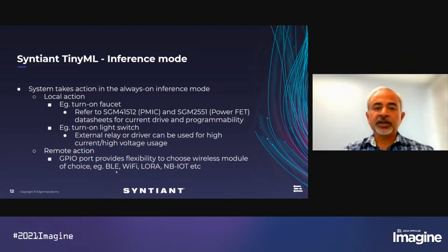Now you can also choose a BLE interface, you can use Wi-Fi, as well as you can use NB-IoT modules, GSM modules, whichever you like. So we did not put BLE on the board, which sometimes people would do. But if they don't really use BLE, then they are paying for this extra component, and maybe taking some power, which is wasted power. So this is the reason why we separated out the RF connectivity and didn't put it on the board. Not to mention that it guarantees privacy. So just on the board itself, it's 100% guaranteed. It's designed for privacy.